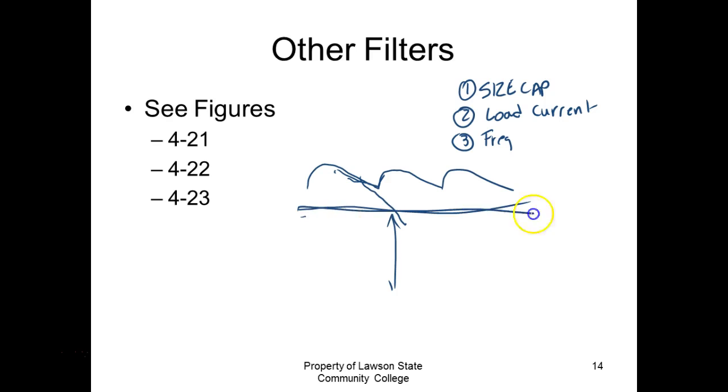So I can always clip that off, right? So if this down here is 7 volts, and I regulate it to plus 5 volts, I'm okay. But if this ever comes down there and I don't choose the right capacitor, or if I try to load it down too much, as soon as this gets down to there, if I were to look at my output, it'd be set at a nice, pretty 5 volts, and then it would dip right there. Because it can't add voltage, it can only strip it off, and that's what a regulator does. It regulates below the valley of the ripple voltage.